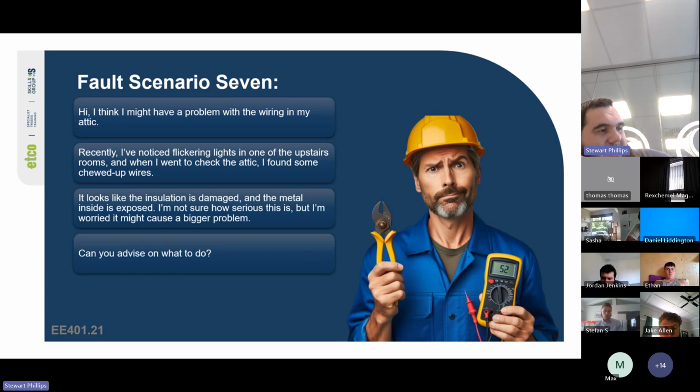Yeah, well, usually if the client's telling you they've seen exposed wiring, it's like, well, cool, there's an insulation breakdown. They've kind of solved the fault finding part for you. But just because the symptoms are one thing doesn't necessarily always mean it's that.